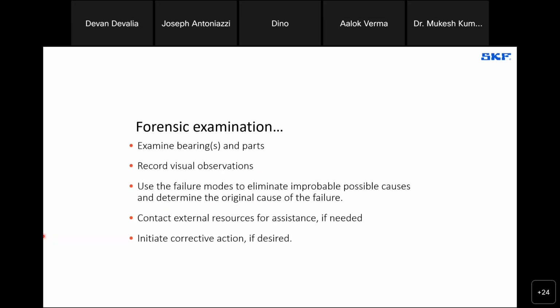All right. So the bearing failure analysis portion is simply a piece of the bigger root cause failure analysis discussion, the bigger puzzle. For those familiar with RCFA, it's important to address the true root cause of a failure and not treat the symptom of the failure. So there are many well-proven methods. I'm not going to go into them. Suffice it to say, we know there are tools that you can use to drill down to a root cause, such as the 5 whys, fault tree analysis, cause and effect, etc.